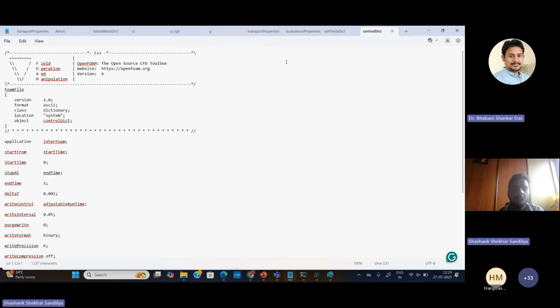is that you have to create the geometry, meshing, set the boundary conditions and set field, and then visualize the output through ParaView. Those skills are important, and during simulation this decomposing tool will also be required. If you have 8 GB RAM or 16 GB RAM on your laptop, to perform more accurately you can decompose the things. Okay, thank you, Sasank.